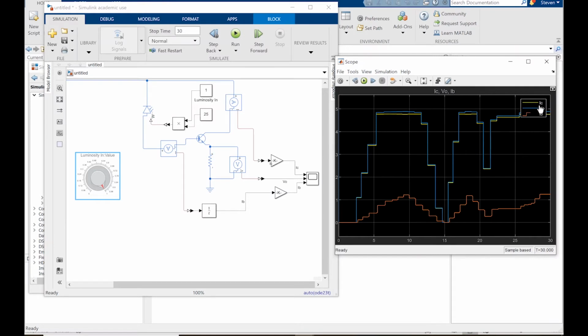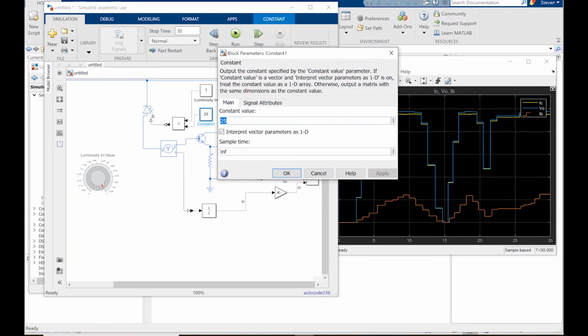So you can see the current and the voltage of the load. They're identical because it's the same math. It's 1,000 times 0.005. Yeah, it's 5 milliamps, not 0.5 milliamps. Math. Here you can see the red line is the base current, and it's 10 times less, but it does track along with essentially the same waveform.